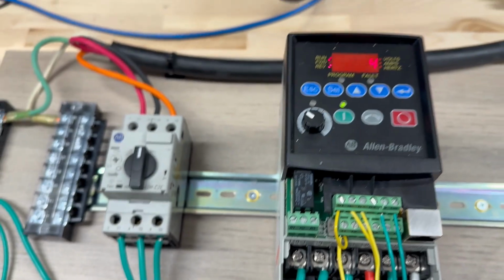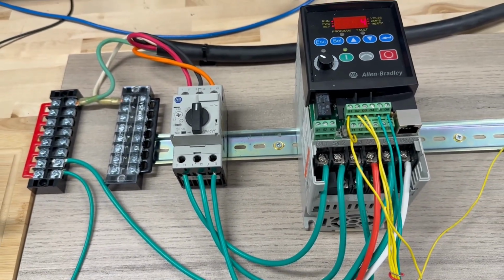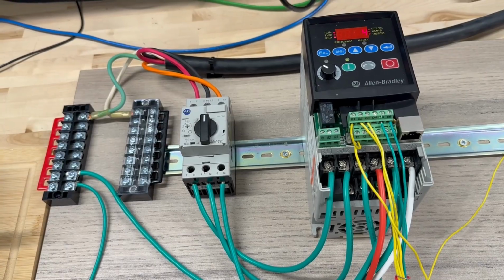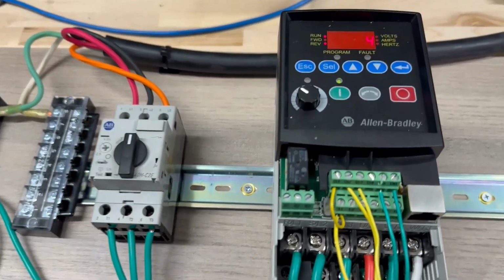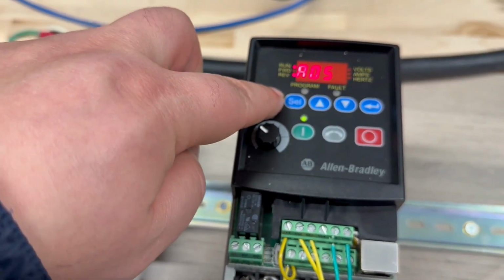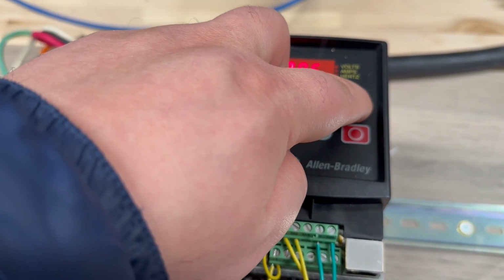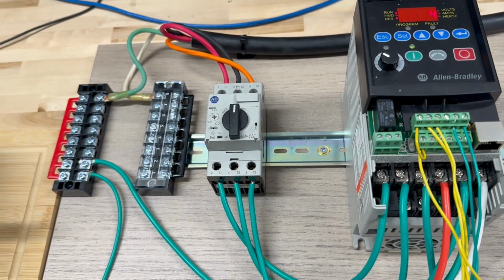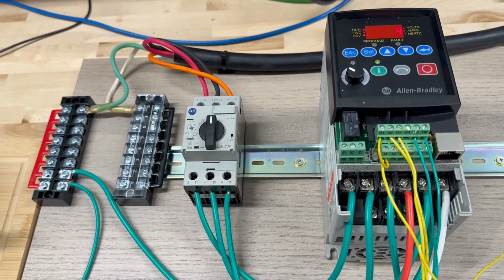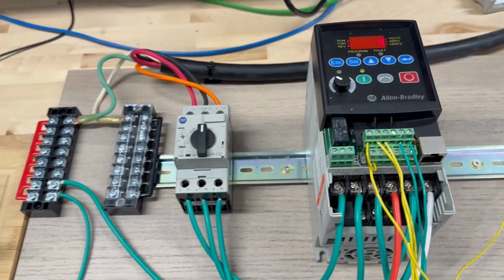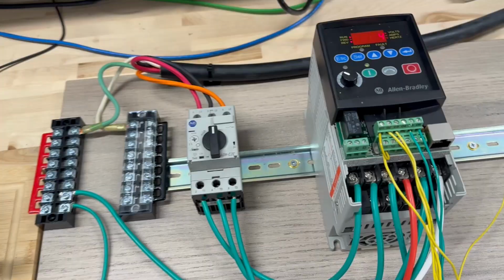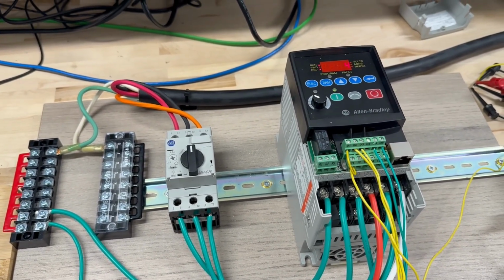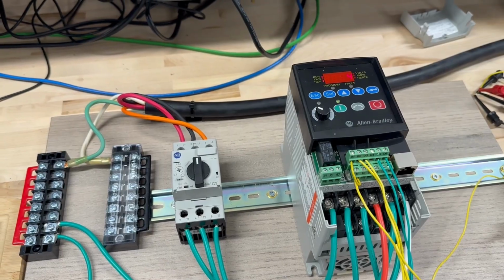If you check the data sheet, A51 is digital input. The setting for preset frequency should be 4, which is the default. That's correct. Now let's do A52 for digital terminal 6. It is also 4, which is preset frequency. They are already all set. Let's see what else we need to adjust. Let's take a look at the table.